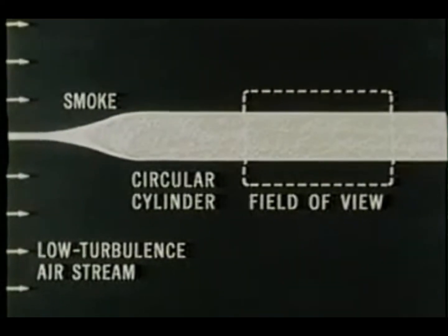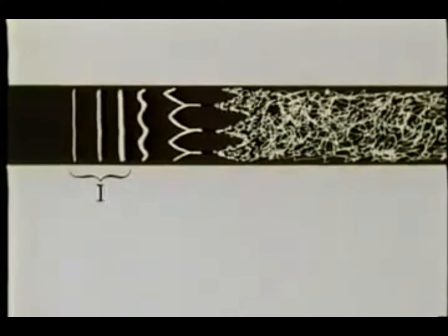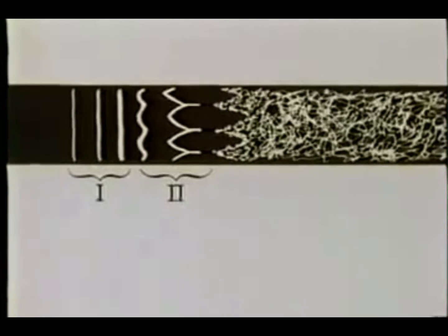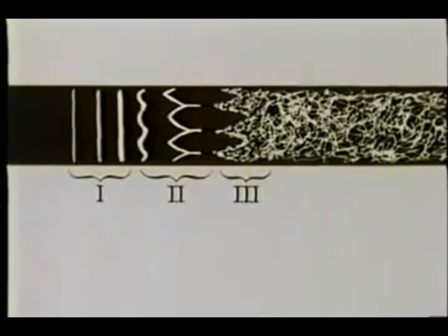The steps in the transition are very complicated and interdependent. Of nearly two-dimensional waves, the Tollmien-Schlichting waves, followed by the appearance and growth of three-dimensional disturbances associated with streamwise vorticity. Then turbulent spots can be seen. And finally, fully turbulent flow appears. Here, the exact position where growth of two-dimensional disturbances begins depends on random small-scale fluctuations in the flow, and therefore varies with time in a random way.